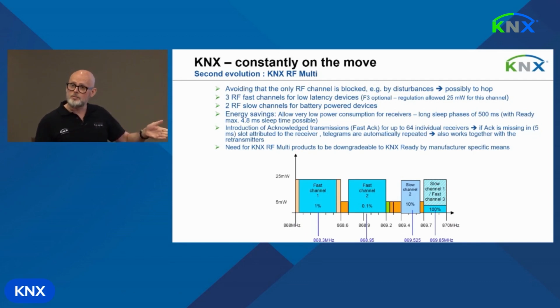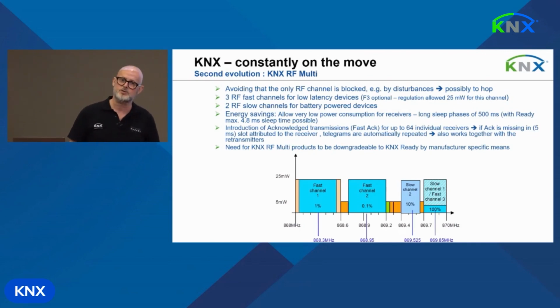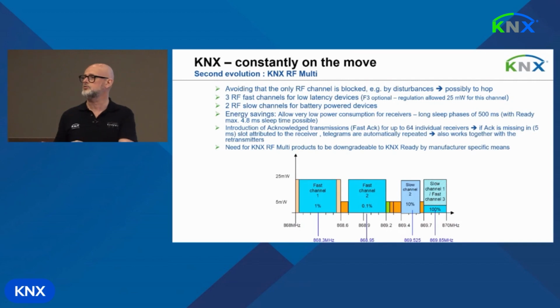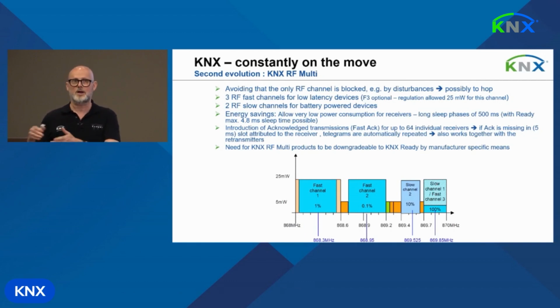Also very important, by introducing KNX radio frequency multi, there was an obligation for manufacturers, if they have multi devices, to be able to downgrade the products to ready. So if you have a ready-only solution and you want to add a multi device to it, then via manufacturer-specific means, you can downgrade the product to become ready.